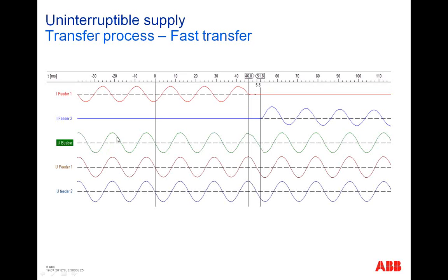Now please have a look at the busbar. You see here, the breaker is opened, the busbar is isolated, and you see exactly this is the feedback energy from the rotating machines during this time gap. And now an overview of the busbar voltage, and you see nearly nothing. You see also nearly nothing during the transfer. So you can imagine you will not lose any connected load or process on the busbar during the transfer.